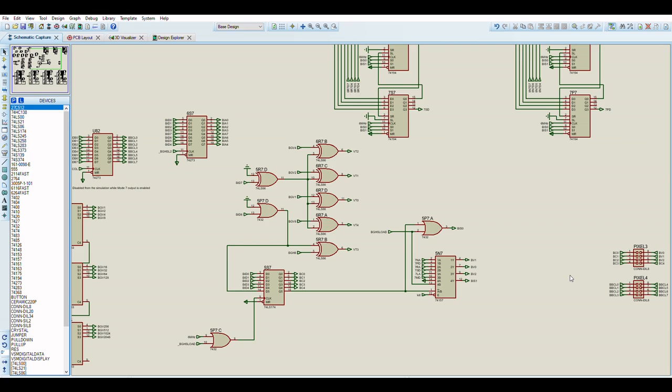The only layer of the board that decides whether or not pixels are transparent is the Sprite board, because it has the Sprite buffer RAM for the scan line, and the Sprite horizontal position can render pixels anywhere within this scan line, so it needs that inbuilt transparent pixel test with the Sprite, because you could have all of the sprites bunched up on top of each other, so you need a way of calculating which Sprite pixel has priority.